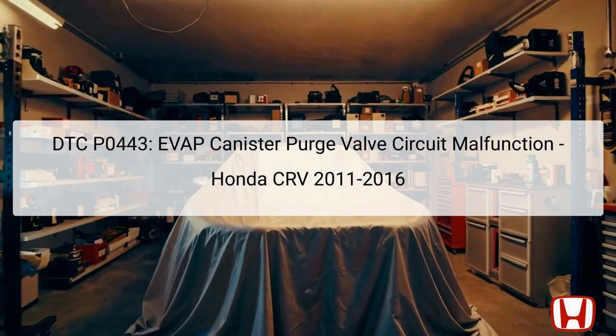Today, we will address the DTC P0443, which indicates a malfunction in the EVAP Canister Purge valve circuit in the Honda CRV models from 2011 to 2016. This error often stems from issues within the evaporative emission control system, EVAP, which plays a crucial role in minimizing the vehicle's emissions by trapping fuel vapors from the fuel tank and subsequently venting them into the engine for combustion.